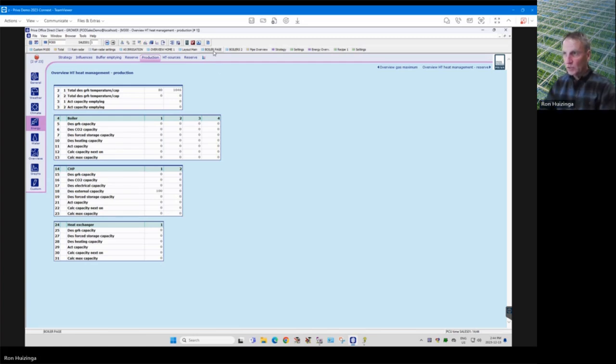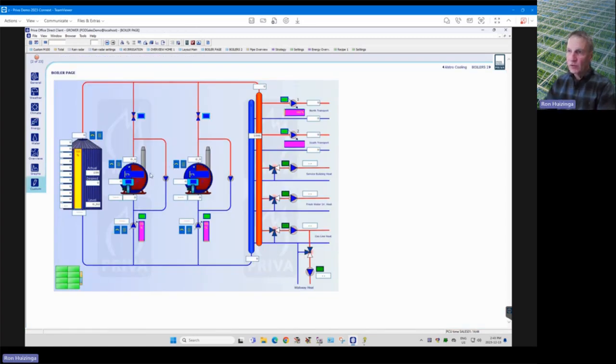Yes. So typically, if the boiler is off, it should close this valve, and this water level is up. Then this red pipe here is down low. It's always sitting in the water. So basically, when the transport pumps run, or the greenhouse, or any pump that's on this manifold, then they'll suck the water out of this tank.